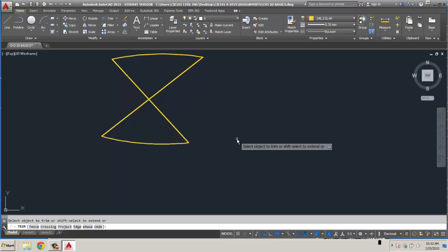So rather, if you look on the page, they talk about creating elliptical arcs. Sometimes it's better to just create the ellipse, bring some lines into it, and then trim it off where you want to, rather than just going through all of the setting of points and getting things just right. Just use your trim command.